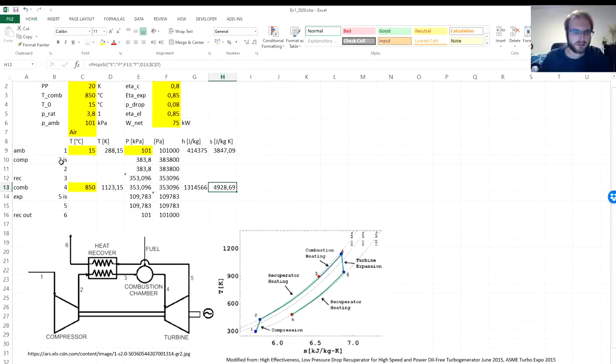And now, how do we handle point 2 isentropic after ideal compression? Well, since it's called isentropic, ideal compression is an isentropic change, so that means that the entropy will stay the same. Now for this auxiliary node we have entropy and we have pressure.